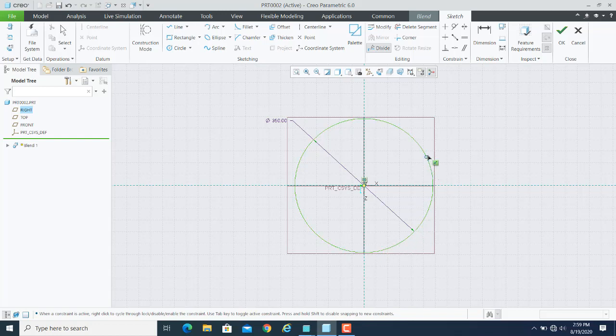on that circumferential area. So I can take any point as my dividing point. As we need 4 points, I will start with the quadrants. So this is, let us say, my first dividing point. This is the second dividing point. This is third, and this one is the next one. So I have divided this circle into 4 segments. Right now we do not have a circle, but we do have 4 arcs. So we have 4 points, and then those 4 points can be joined with a square or rectangle.